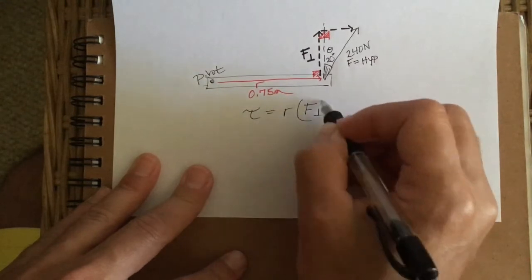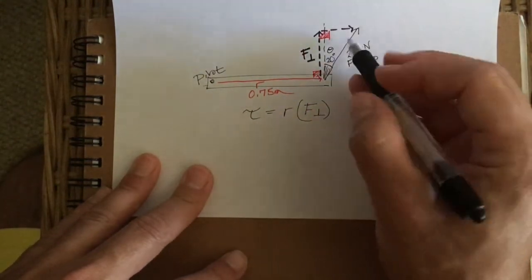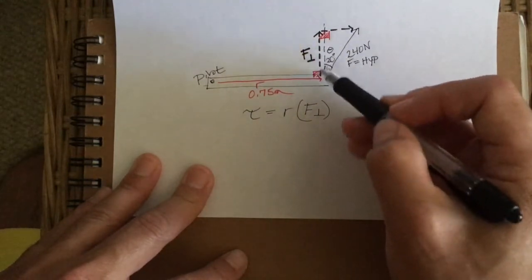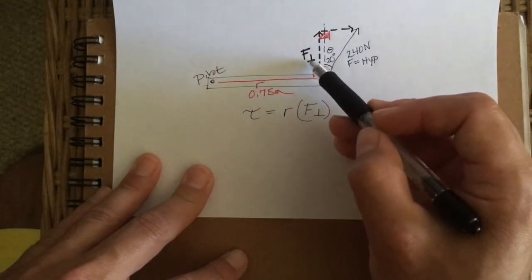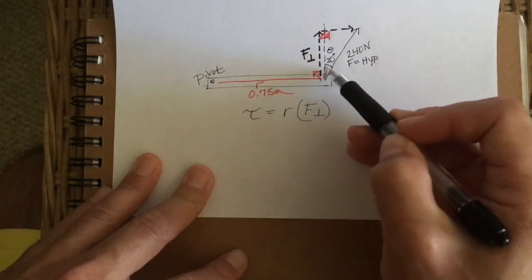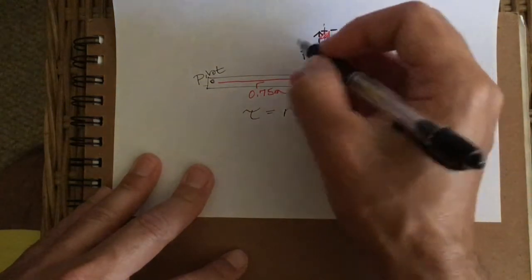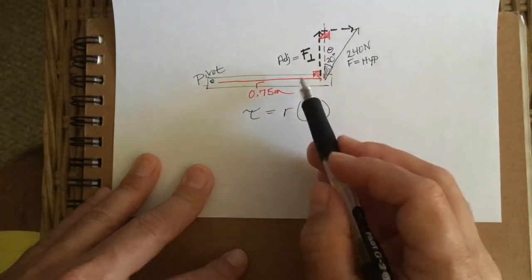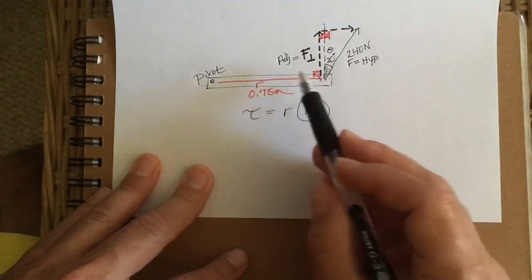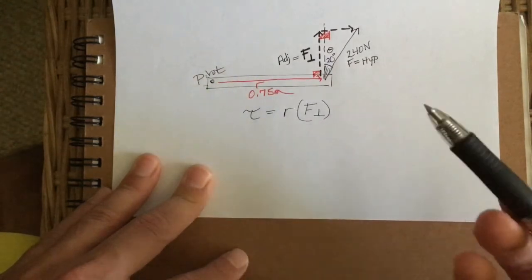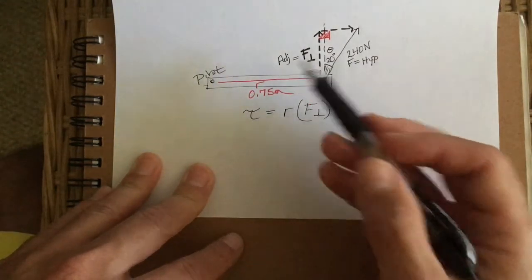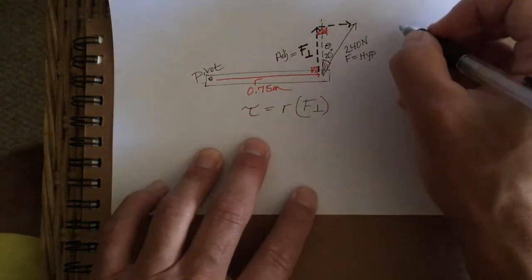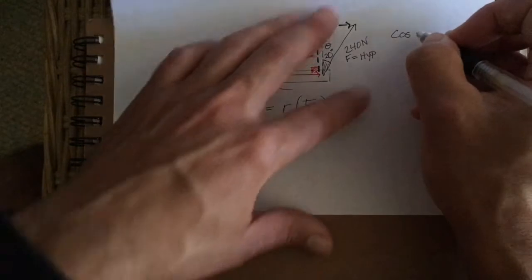Coming up to this problem, we see that the 90-degree angle is here. This force is split into an Fy and Fx. Fy is adjacent, right, to this 20 degrees. So I'm going to call this side the adjacent. And you can see what's going to happen because I'm using 20 degrees now, and this is the adjacent, that's going to change the formula, right? I have a hypotenuse. I want to know the adjacent, so I'm going to grab my cosine formula.